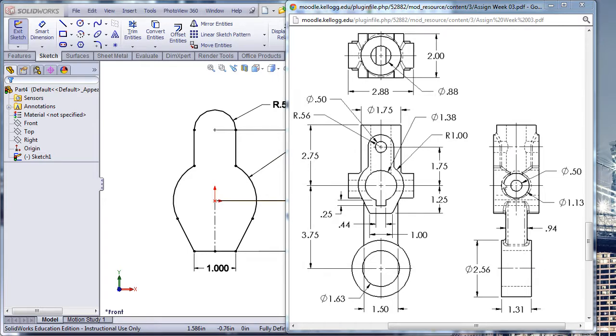What that means for us is when I extrude, think of this sketch plane right here for my first feature. When I extrude that, I can't extrude it in a single blind direction. I'm going to have to do all kind of mid-plane extrudes here off the front plane. It's the only way this part will come together because I don't have dimensional information establishing, say, the relationship between this edge and this edge. So we have to assume that everything is symmetrical or mid-planed on this part.